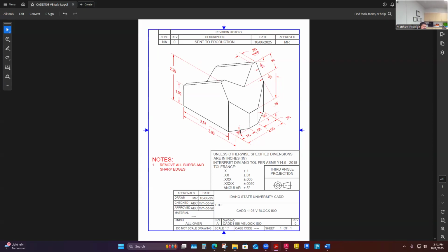Kind of makes me think, I think I was pointing out in class that this is a 30, 60, 90 degrees. So technically I should be able to go over here and do 60 degrees over. I'm not going to do that. I'm just going to use the data I have here and go over to this far right side edge on the top view and put in 0.5 inches, half an inch long. And then I'm going to turn that back 30 degrees to the back and front view. So let me do that.